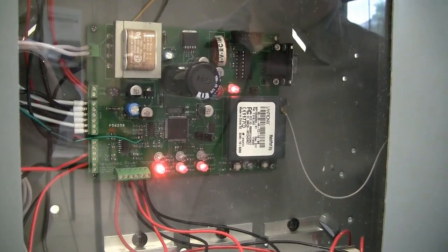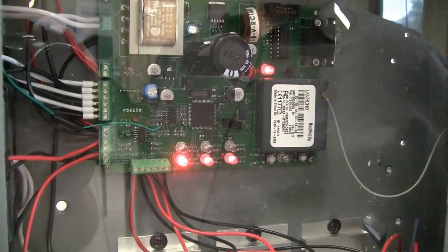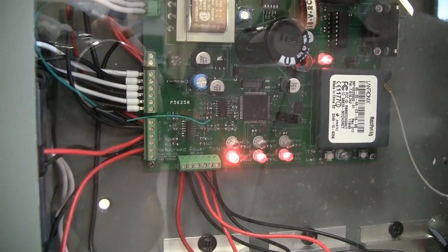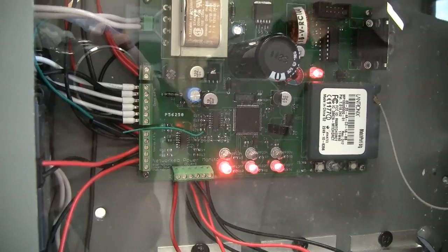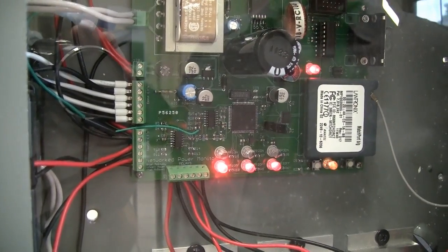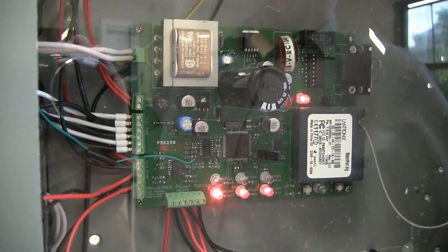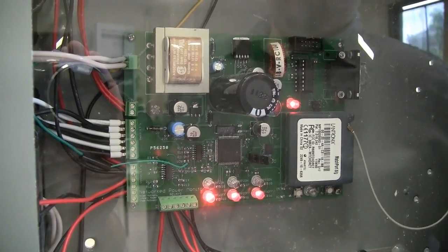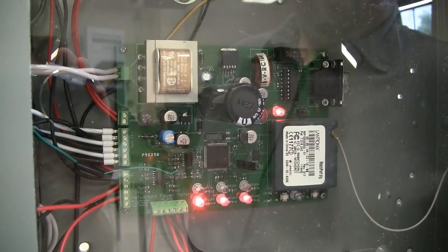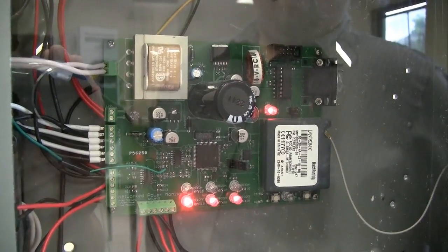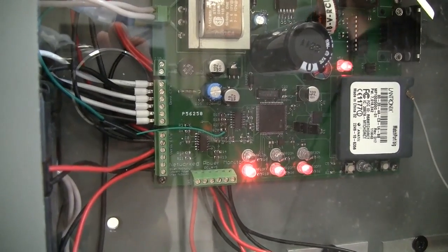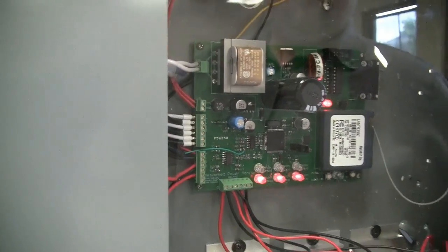The second use for the MAX232 chip is to provide negative voltages. As part of the current sensing circuit, there are transducers that output a small sinusoidal wave that's proportional to the incoming current. This wave is too small to trigger the zero crossing circuit used to calculate the power factor, so we require the use of an op-amp amplifier. Op-amp amplifiers require negative voltages. The MAX232 was an easy, efficient way of providing a negative voltage for that circuit.